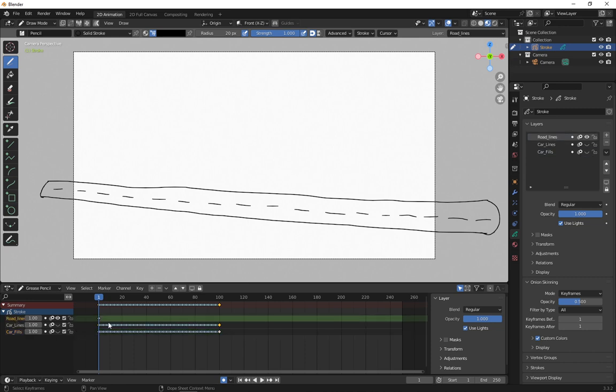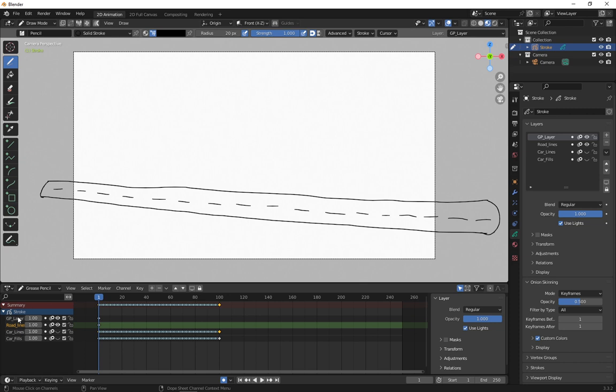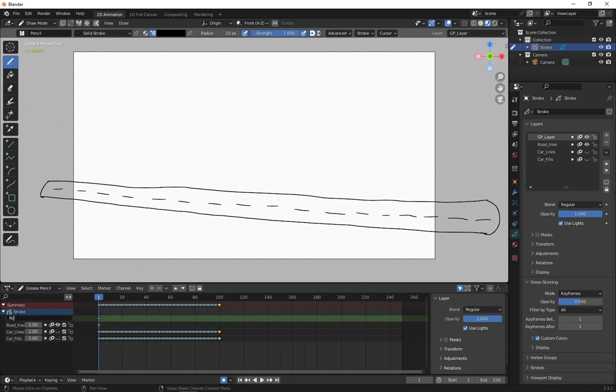So we've got our road line, we've drawn our lines. We're going to add a layer, okay, and it's going to be road fill. And now this layer, we actually want it below. Normally you put the fills below so that the lines appear superimposed on top of the colors. Very simple. All we do is go over here now to, again, the Object Data Properties window. We select the layer, and we hit the down arrow.